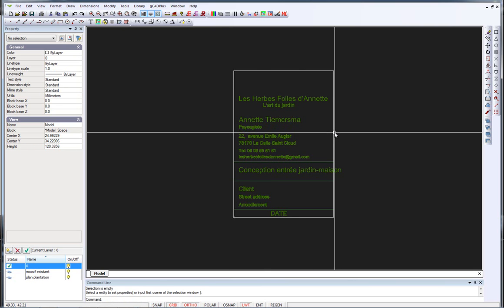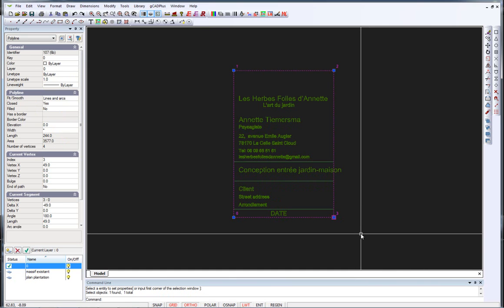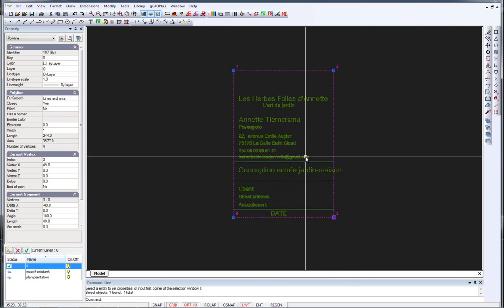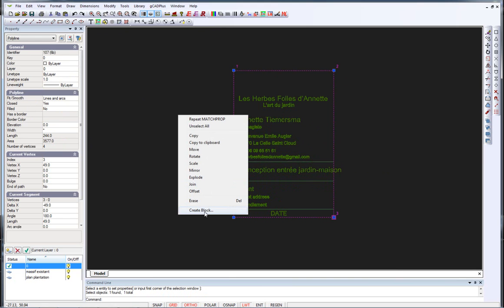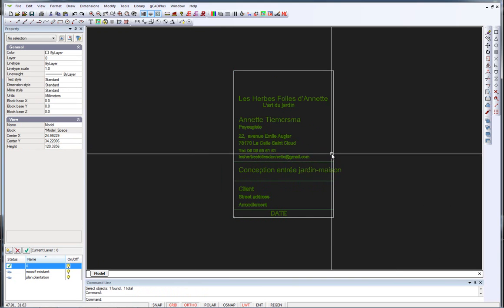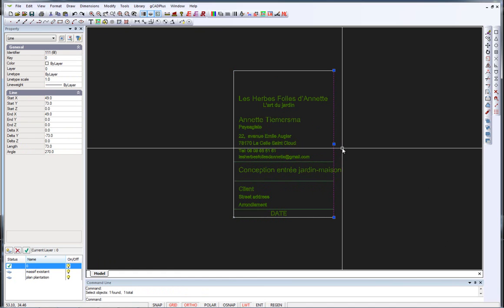We would need to change the width of our box just a little. So here's its elevation and width. That's a polyline again, so we need to explode it, and then we can pick this individual line here.